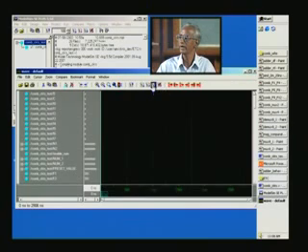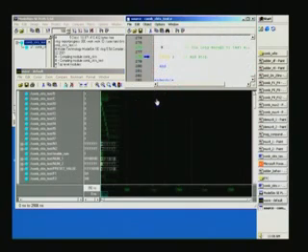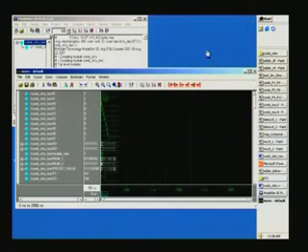What will happen if you give run all? So I click on run all. You see a waveform pattern here, and it has also opened your combinational circuits test bench .v file, and you can see that it has stopped at the last statement called stop, right? And I'm afraid you will not be in a position to read this once again. Anyway, we have the actual bloated-up combinational circuits file here. We'll see that later. Now that we don't need this .v file, we'll remove that window.